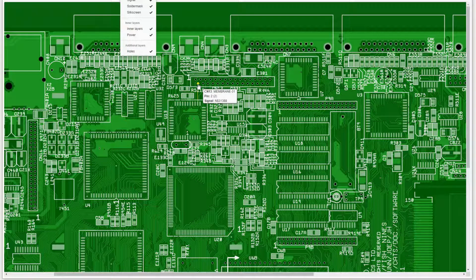The fear with removing this connector, if you decided to do that, is you need to make sure every pin is fully released from the via on the PCB. If you desoldered all of these and the pin right here was still attached to one of the sides of the via, still had a solder connection, and you pried on that connector, the trace that's lighting up in yellow there, you have good odds of actually lifting that trace off the board.